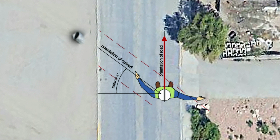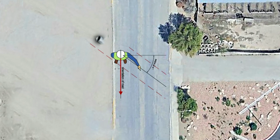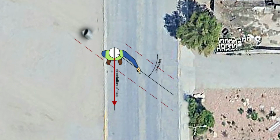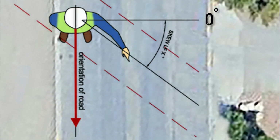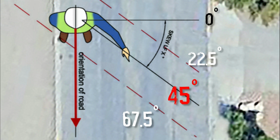If you try to do it with the other arm, it is not possible or it's very uncomfortable. In this scenario, the culvert presents a left skew. When traveling in the opposite direction, you will notice that the leftward skew persists in orientation. Estimate the degree of skew visually, rounding to the nearest 22.5 degrees.